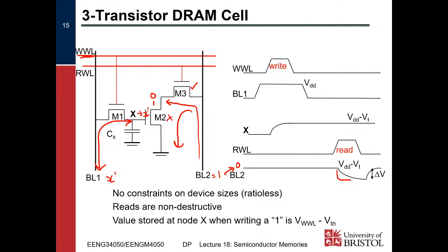We see a significant drop, and hence we're able to read from the cell, right? And then we introduce some sense amplifiers to ensure that voltage drop, because we won't go all the way down to 0, just far enough down for us to notice it.